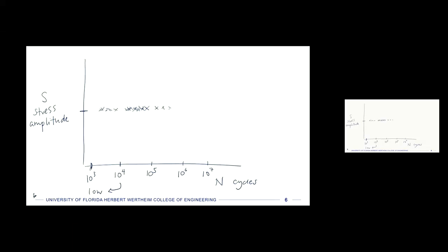Okay. And if we wanted to look at only that experiment and ask what kind of distribution that is, this is normally modeled as a normal or Gaussian distribution, where you have the number of specimens on the y-axis and the cycles that they failed at. If you made a bar plot, you could model that as a normal distribution. And that's one set of experiments at one condition for a bunch of samples.